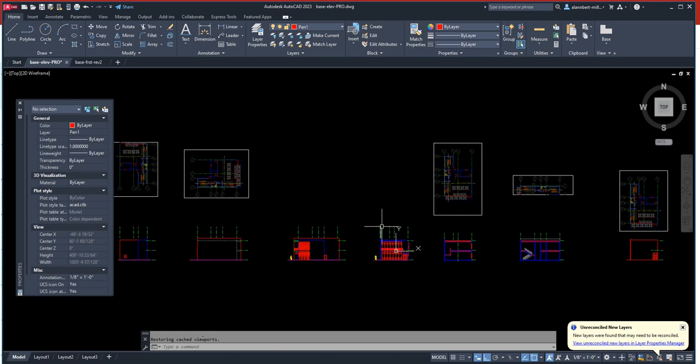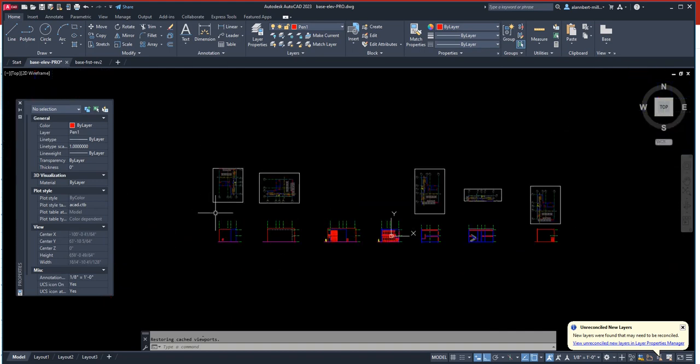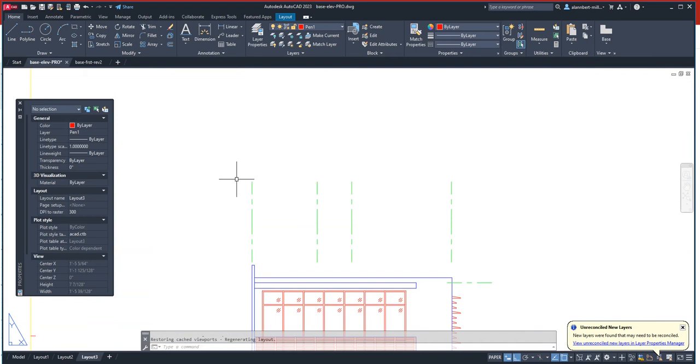Okay, this would also be 1, 2, 3, 4, and then this one would be this E. So this would be E, D, C, B, and then A. All right. So we don't put it in model space. What we do is we actually put it in paper space. So in paper space, we are in control of the actual heights of text.